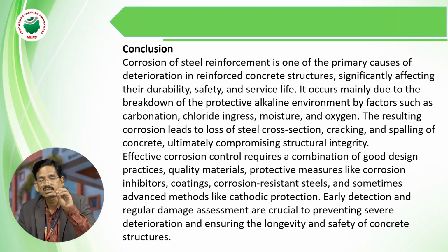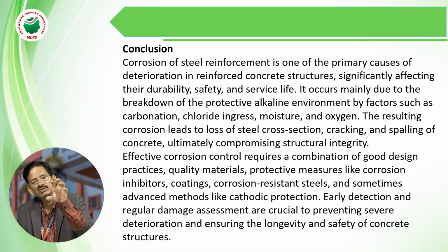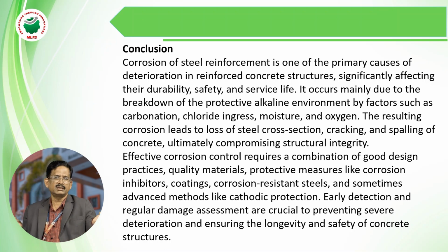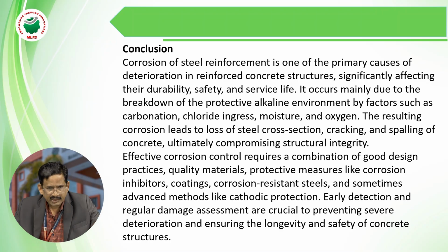Prevention is better than cure. In a similar way, early detection of the corrosion of the reinforcement. If the reinforcement is exposed to the atmosphere, automatically corrosion will develop inside the concrete. So we have to check immediately and take the necessary precautions to fill the gap. Why? Because in structures, at a time we are going to do the slab and beam concrete, a bigger area, so it is not possible to check shuttering inch by inch.